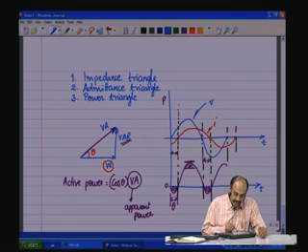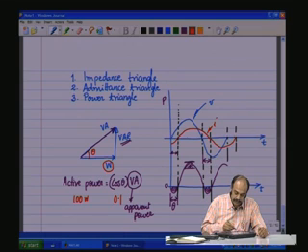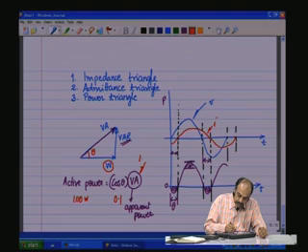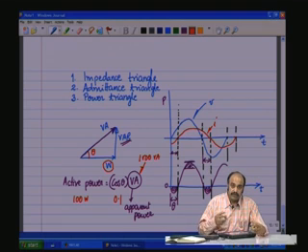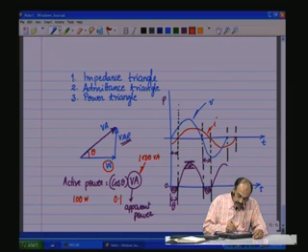So, if cos theta is, let us say for example 0.1, and I want a 100 watt load, what it implies is that the apparent power that you should draw from the source should be 1000 VA. So, my source should be rated for 1000 VA to deliver a 100 watt load if the power factor is poor. This is called poor power factor. This cos theta is called power factor.